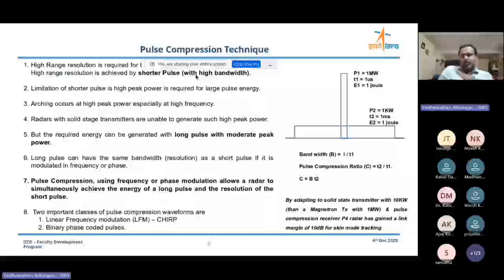Not all signals can be made like that. A signal with known phase information must be transmitted, or a chirp, as we call it in analog, with the required bandwidth. If we transmit a wider chirp signal, after receiving it we can de-chirp it to form a narrow signal, so that the transmitter radiates only a lower average power, whereas the receiver, after compressing, sees an echo equivalent to a peak power and narrower pulse being transmitted. These things can be easily implemented with solid state devices. That is the important thing which is making radars and other systems go beyond their earlier range capability.